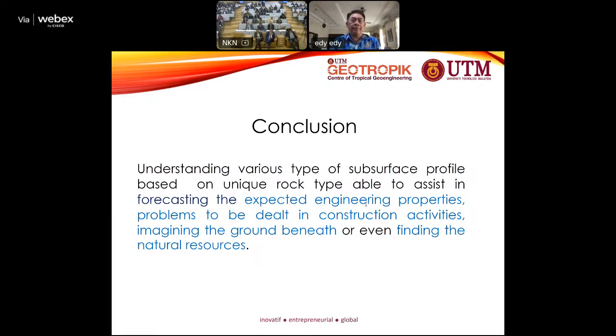Okay, so in general, as we could see just now, the changes between the different types of bedrock and different weathering states carry different parameters and different behavior of the particular zones. So the understanding of the subsurface profile from various backgrounds is very important and crucial, and is also helpful for us to understand the expected engineering properties and problems that could be dealt with. We also could come up with potential mitigation measures to reduce the potential risk at the different types of rocks.